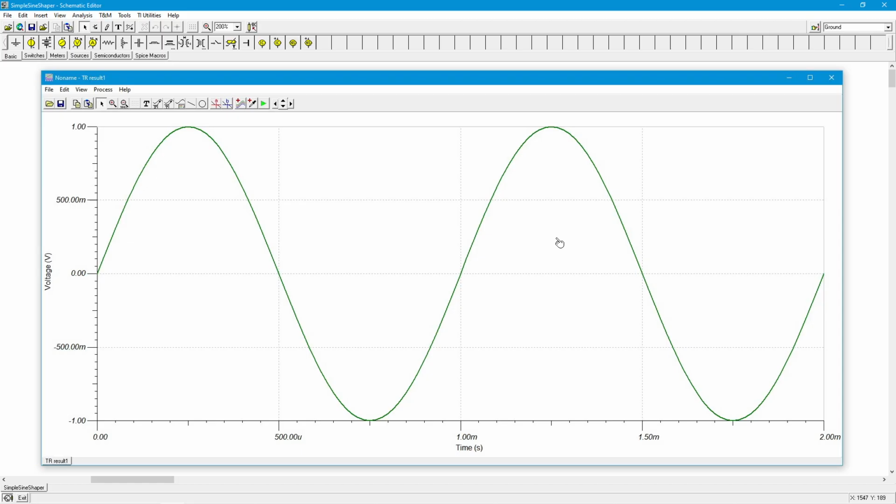So the trick here is to exploit the true characteristic of a diode. What do I mean by the true characteristic? Well, typically when we think of diodes, we think of a simple curve describing them that is not allowing current through at small voltages. Then when we hit a voltage up around 6 or 7/10 of a volt, the diode turns on and allows current to flow. It's a simple little model. It works pretty well. But remember, it's just a model.